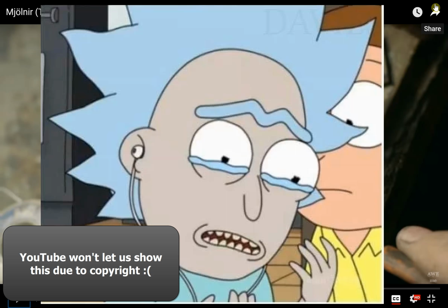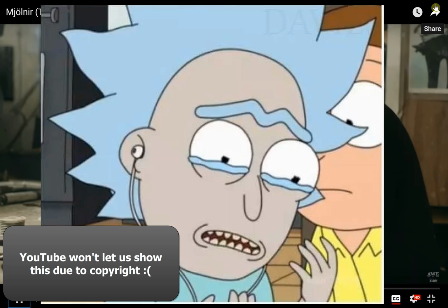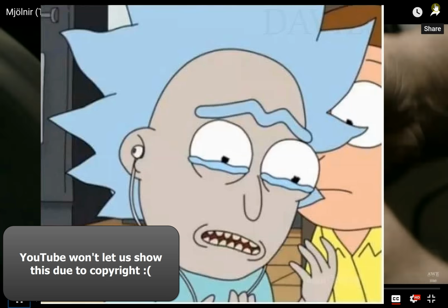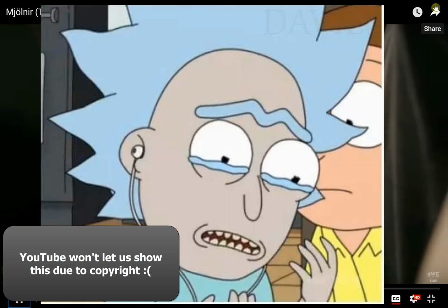heat, and surface energy is going to draw that in the cracks between it. So all that extra material, that's why he's torching it. It's getting sucked into the gap between there to reduce surface area, and then it solidifies just like any other solder does, and you've basically done a large-scale solder job with this, right? So that's going to make it stick. You have to clean all that goop off afterwards, so that's them polishing it. But it's a nice way to bond metal to metal, is brazing.